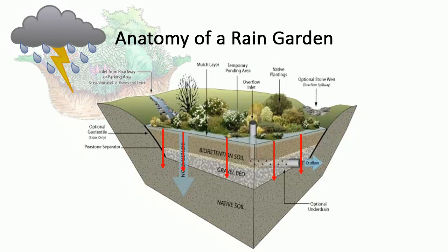The rainwater infiltrates through a permeable soil mixture called bioretention soil, which is designed for drainage and water retention capabilities. Typically, the bioretention soil is a mixture of the native soil with some fraction of sand, loam, or organic material mixed in. A gravel bed is placed beneath the bioretention soil to allow for deep infiltration and groundwater recharge. An underdrain is included in some designs to prevent excessive ponding when the bioretention soil or underlying native soil have difficulties draining water and extra drainage capacity is needed.